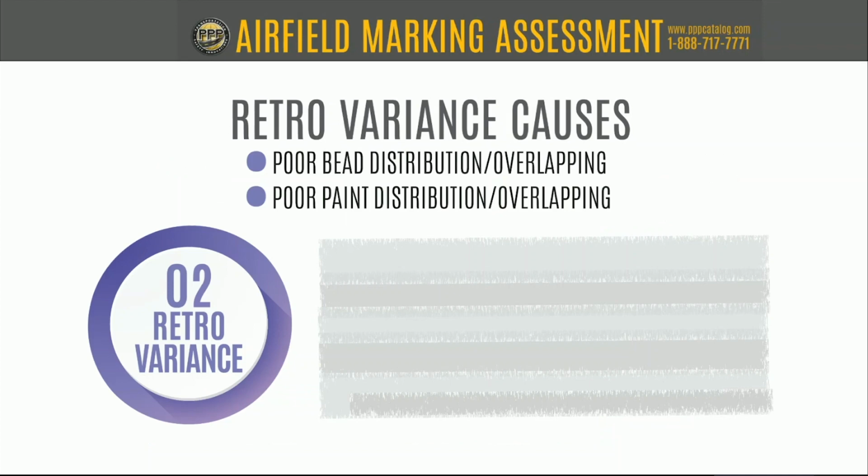But most of the time, what we found is that it ultimately comes down to the paint thickness, because again, you have beads that are in a double thickness, so they're embedded deeper. That reduces their reflectivity, and then you have them in the normal area where it's single thickness, so they're brighter, so you get that duller, brighter pattern across the line. But yeah, I think Mike, you've had some success with using.